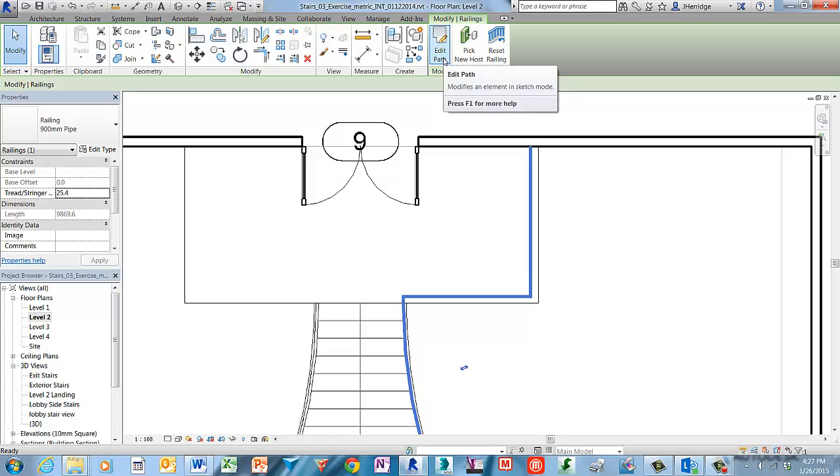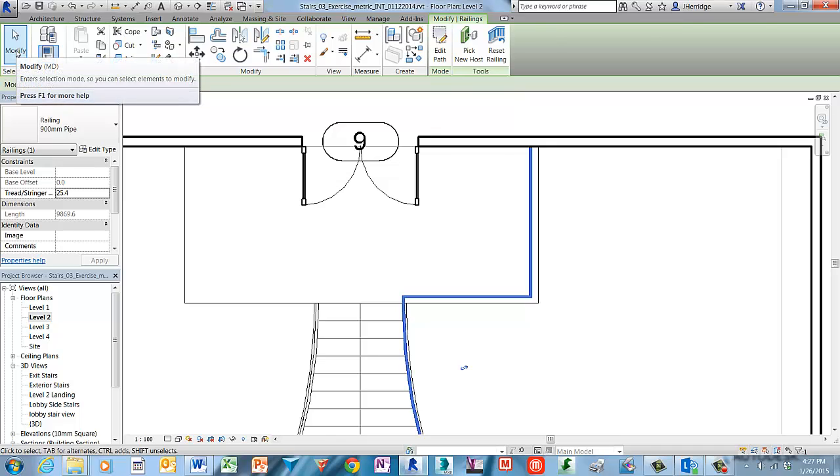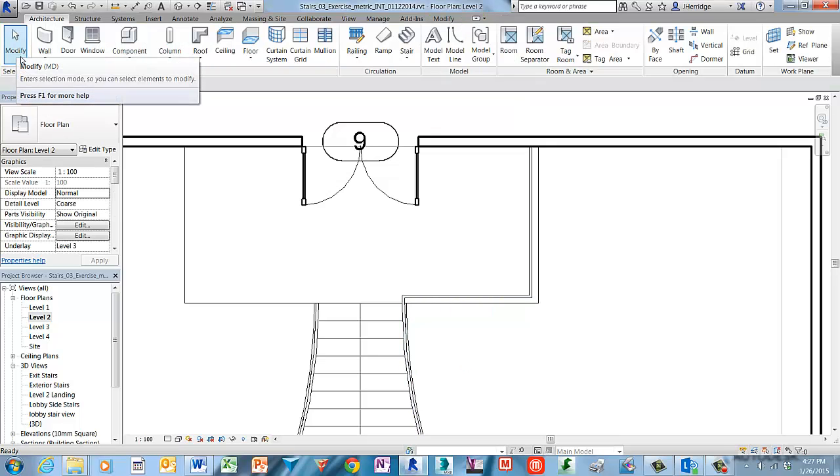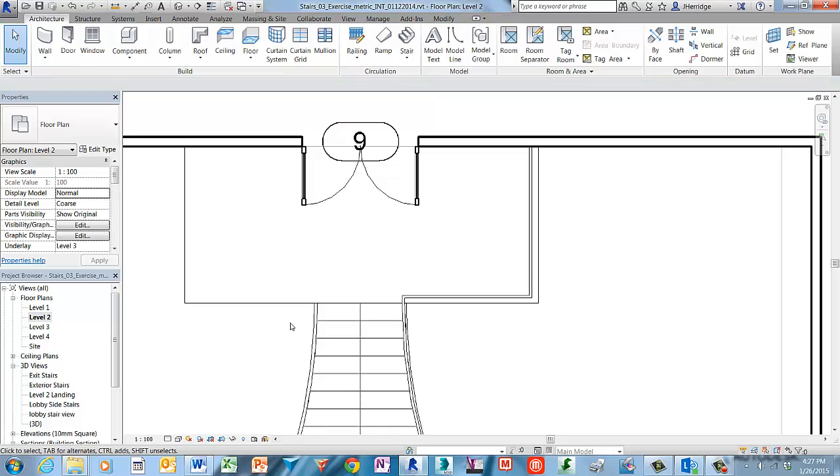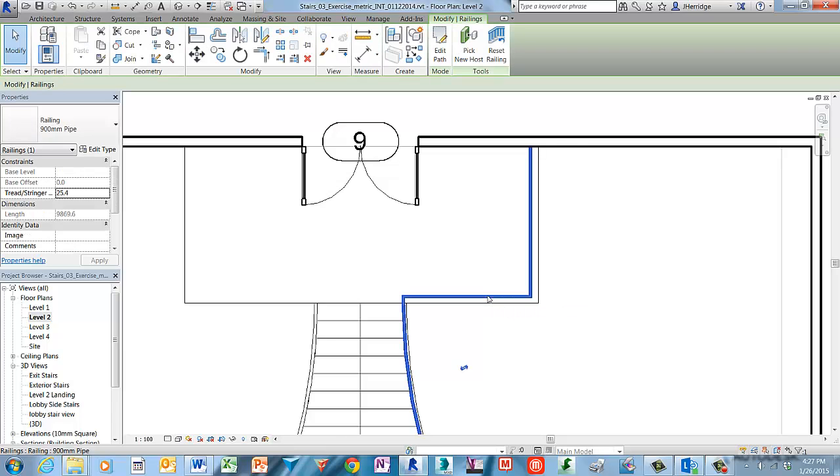Next, we will delete the railing that's on the left side and replace it with a copy that we just created. So choose Modify to end the command. Move back into the canvas window, go ahead and left click to select the left railing and then hit the delete key to remove it. Next, move over to the railing that we just created.